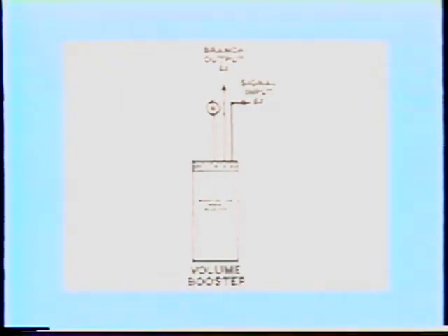The branch pressure is shown as equal to the input at S1. The output pressure of the booster relay can be advanced or retarded in relation to the input signal by adjusting the bias adjustment. This can be used for staging or sequencing purposes.